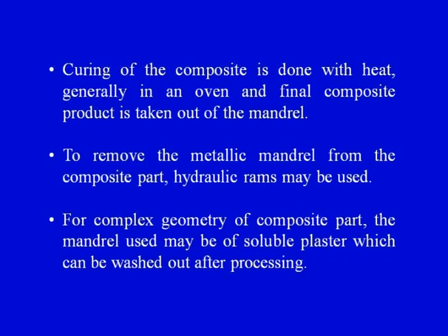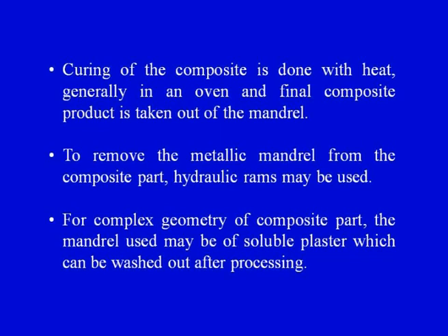Curing of the composite, that is the process of solidification of the composite, is done with heat. So we can have a heating arrangement around the filament wound product, generally in an oven, and the final composite product is taken out of the mandrel. So we then finally have to take out the composite product from the mandrel.